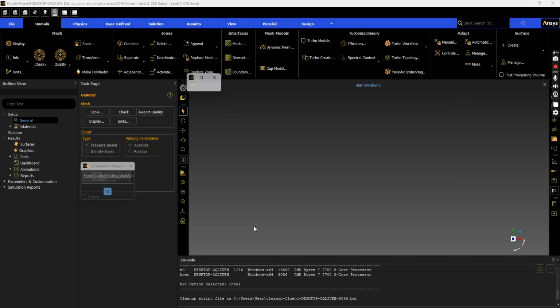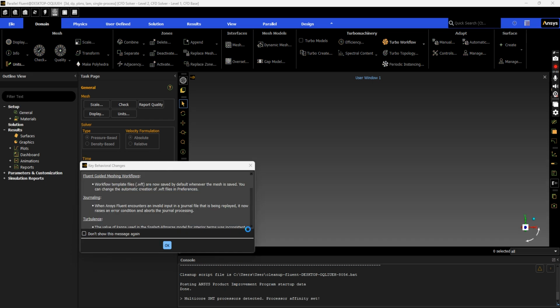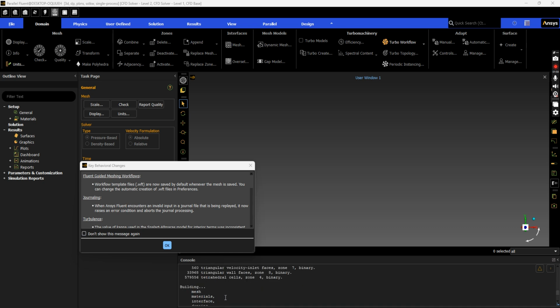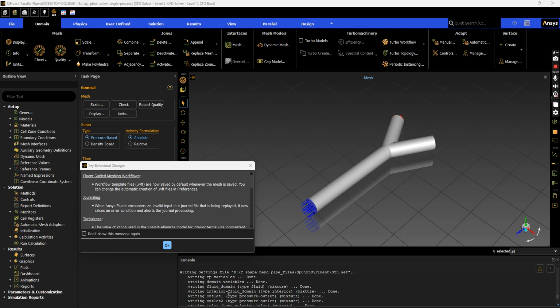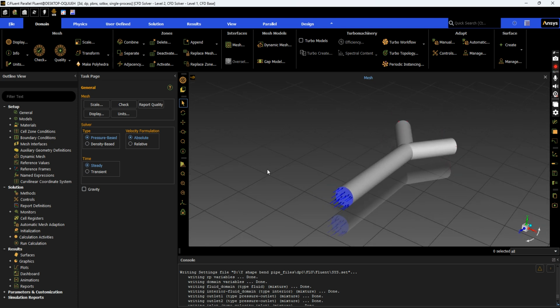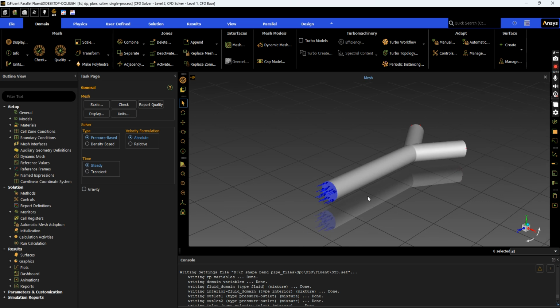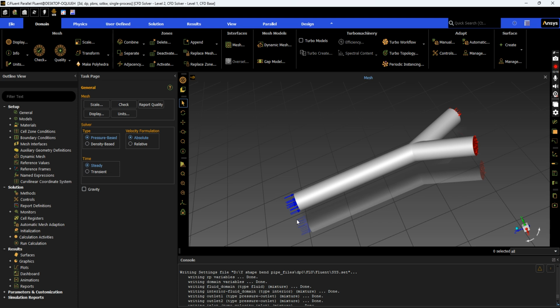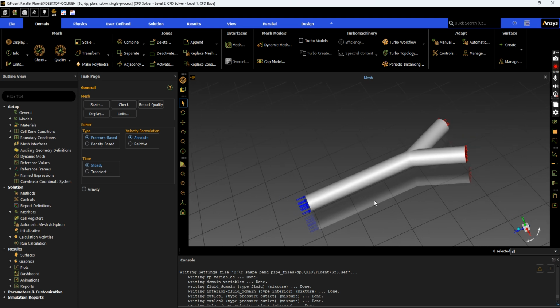The Fluent is loading the file. So you can see, okay, so our mesh file is loaded. If you have done proper name selection, you should see these arrows. If you hadn't done the proper name selection, you will not be seeing these arrows, and that is quite problematic. So remember, must do name selection in Design Modeler or in ANSYS meshing before coming into Fluent.